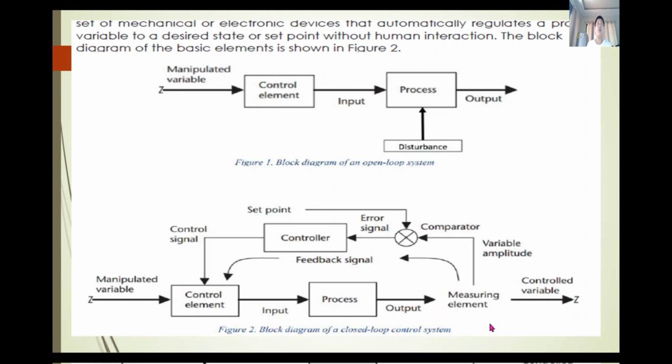So any deviation, or let's say here in the system of jacket cooling water of the main engine, the output or the outlet cooling water temperature of the main engine is usually 80 degrees Celsius, especially on modern ships, because the metal is more durable nowadays.